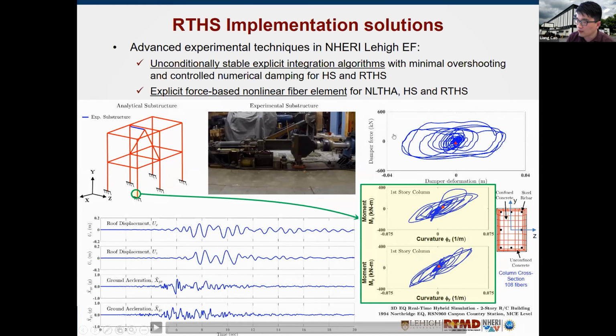First, you can see from the damping energy dissipation that the viscous damper dissipates a lot of energy under earthquake. And third, if you look at the moment curvature, you see the first-story column has highly nonlinear behavior. This highlights the importance of why we're using nonlinear elements. We have to model the structure with nonlinear elements to capture the key features of the structural behavior.